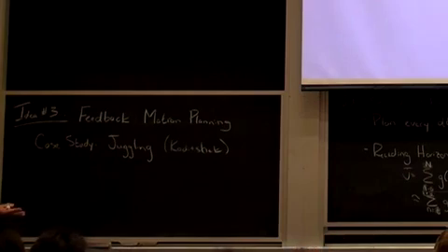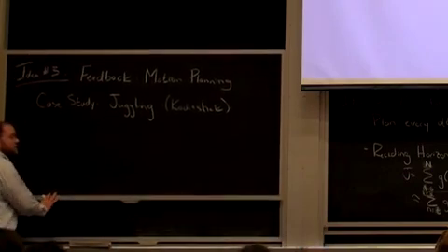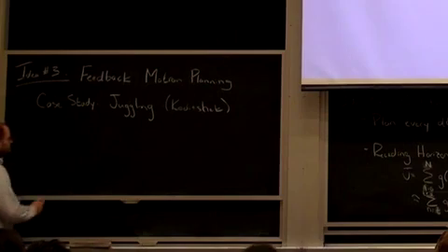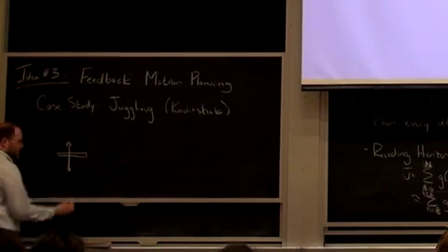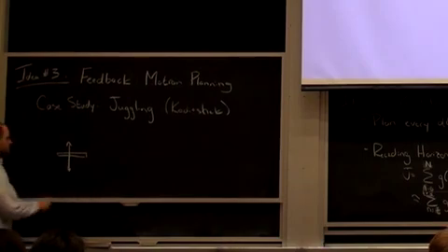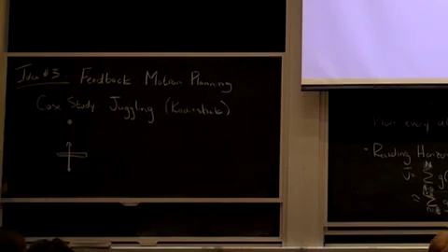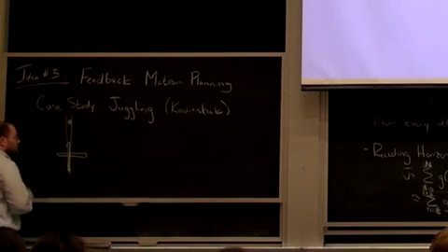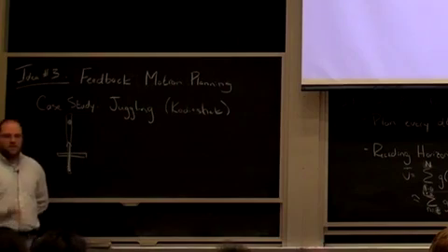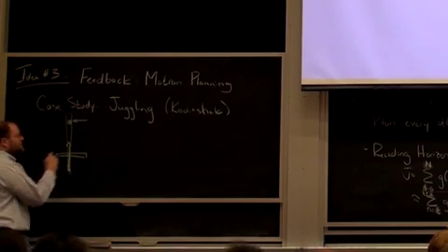Let's think about the problem of making a robot juggle. The first thing you need to think about, let's make a one-dimensional juggler. So we've got a paddle here, constrained to live in this plane, and we've got a ball, also constrained to live in that plane. If this thing is on a rail, it can only move vertically. Your goal is just to move that paddle to, say, stabilize a bouncing height. Let's say I've got a desired height.